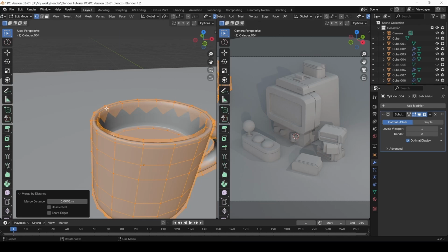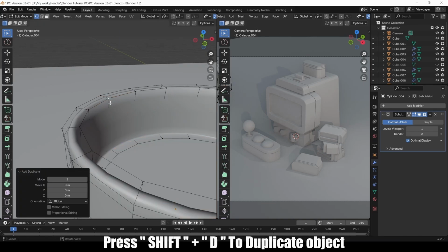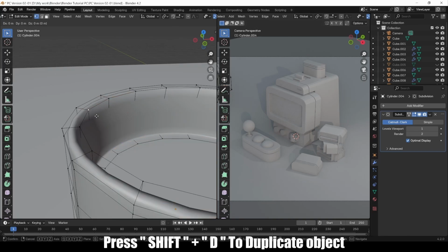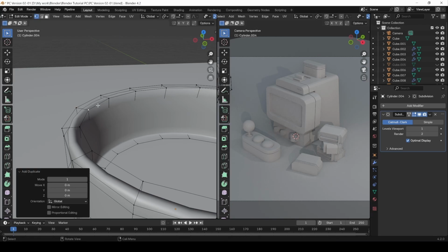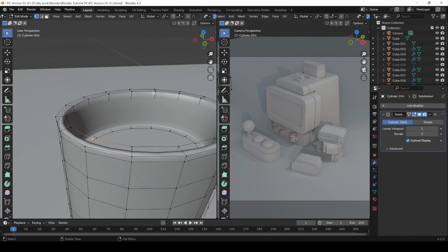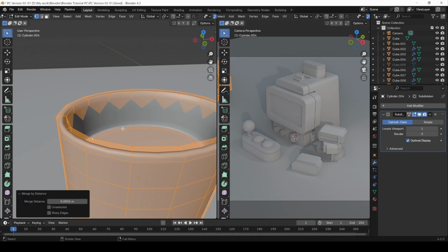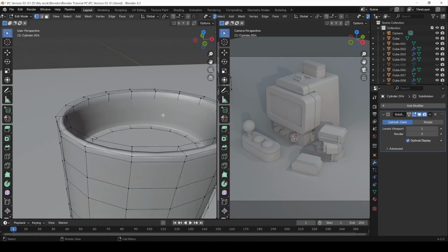Let's say you have two vertices right here duplicated, so let's press this and duplicate this vertex, and here too duplicate and put it down. So now you have two duplicates right here and you don't know where they are. So you are working and you know something is not working, it's probably duplicate vertices or duplicate faces. So what you do is choose every vertex with A, then M, then by distance, and you can see it says remove 2 vertices. It means it merged those two vertices, and you can even choose the merging distance.